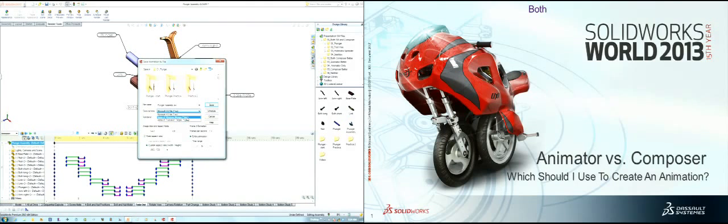We tend to use individual images when we photorealistically render something, because if you do a video file, it has to render each frame, and it keeps them all in memory until the end when it creates the video file. Hopefully you have a lot of RAM, because if you don't, you can lose it after hours of rendering. So most people that do this professionally just render them out as individual images, which are the individual frames. We go to third-party software, like QuickTime Pro for about $30, and it puts them all into a MOV file, and we can play the animation that way.